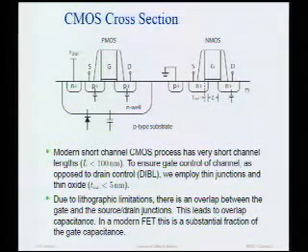Finally, some other non-idealities. Source and drain junctions are reverse bias junctions, right? So they have capacitance, reverse bias diodes. So on the drain side in particular, if I ground my source, I'm going to have a capacitance at the output. You guys have studied that in all the courses you've taken, so you know that very well. What's another non-ideality in the FET? Anybody? Body effect. Exactly, the body effect.